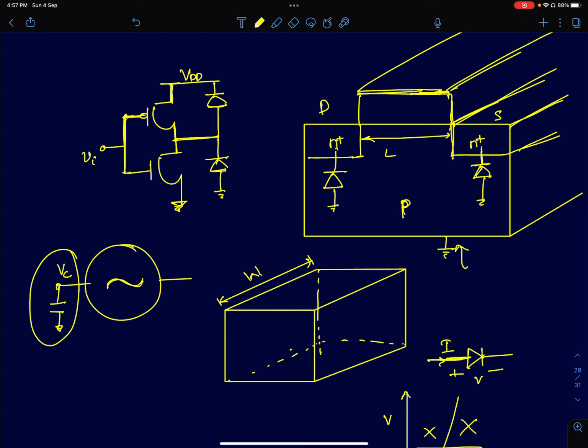And if you have this diode, the diode's leakage current, even though it's cut off and in reverse bias, might discharge this capacitor. To ensure that doesn't happen, the designers had to ensure that most of the diodes had 0 volts across them. How they did that was again a company secret, but it's a very interesting problem.